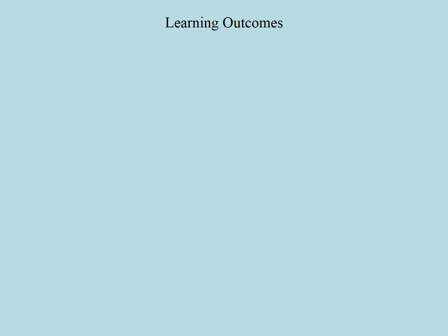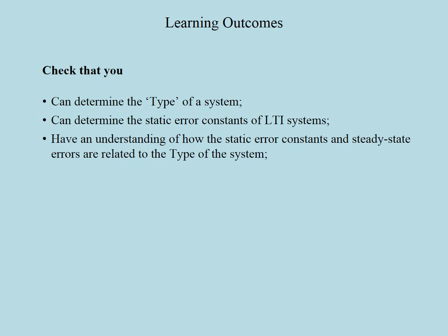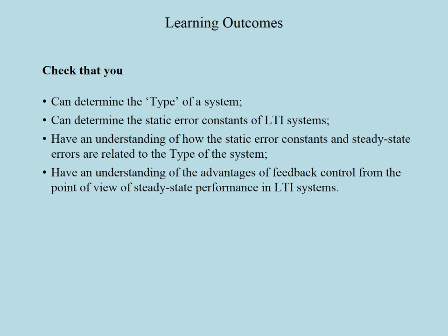Do not forget to study the example problems and questions in your textbook and check that you can determine the type of a system, that you can determine the static error constants of linear time invariant systems, that you have an understanding of how the static error constants and the steady-state errors are related to the type of the system, and have an understanding of the advantages of feedback control from the point of view of steady-state performance in LTI systems.